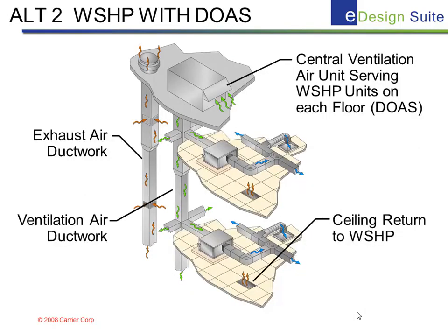Alternate 2 will be a closed-loop water source heat pump system with a gas boiler, heat adder, and a cooling tower to reject loop heat. Each zone will have a reverse cycle water source heat pump unit. The wizards will accurately model the heat recovery feature of this system. Alternate 3 will be identical to Alternate 1 VAV system, except we will utilize a more efficient chiller, and we will add an air side economizer to the air handling units.